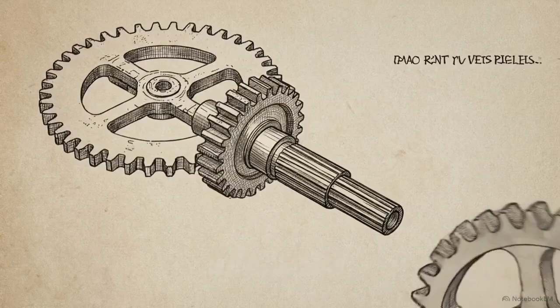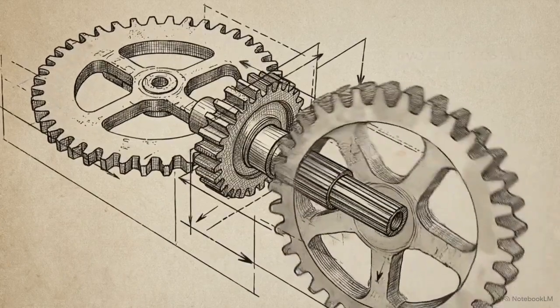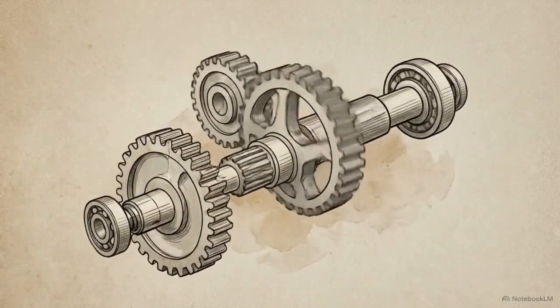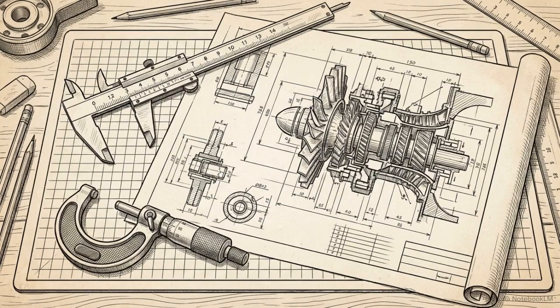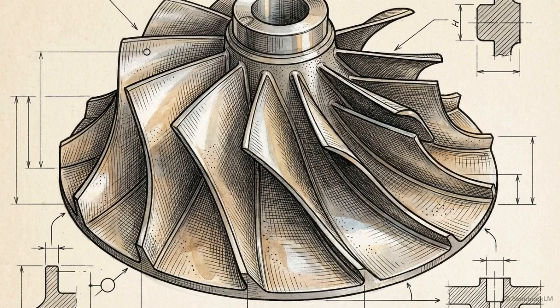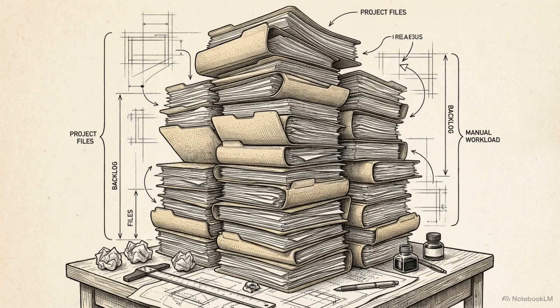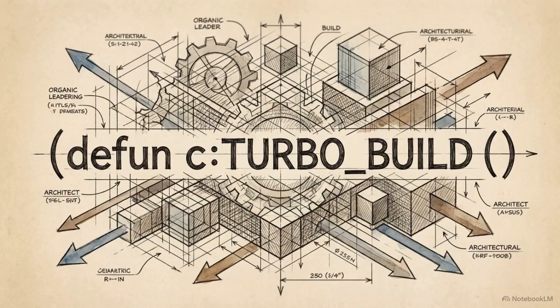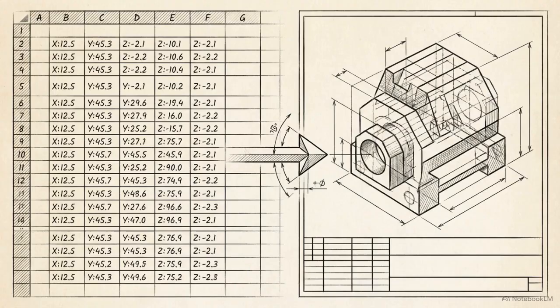Beyond simple batch processing, there is macro-automation. This is the use of AutoLISP to automatically generate complex engineering geometry from raw data. A prime example is found in the mechanical engineering sector, specifically a firm specializing in turbocharger reconditioning. Their manual baseline for this specific task was highly repetitive. It took an engineer over an hour to manually draft, layout, and annotate multi-view component drawings. They implemented a custom AutoLISP solution. This routine reads external spreadsheet data to instantly auto-generate the geometry and format the final drawings.